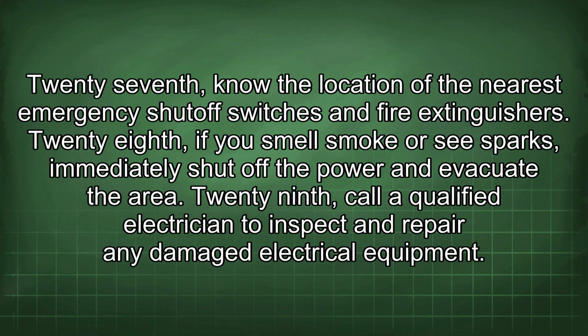28th, if you smell smoke or see sparks, immediately shut off the power and evacuate the area. 29th, call a qualified electrician to inspect and repair any damaged electrical equipment.